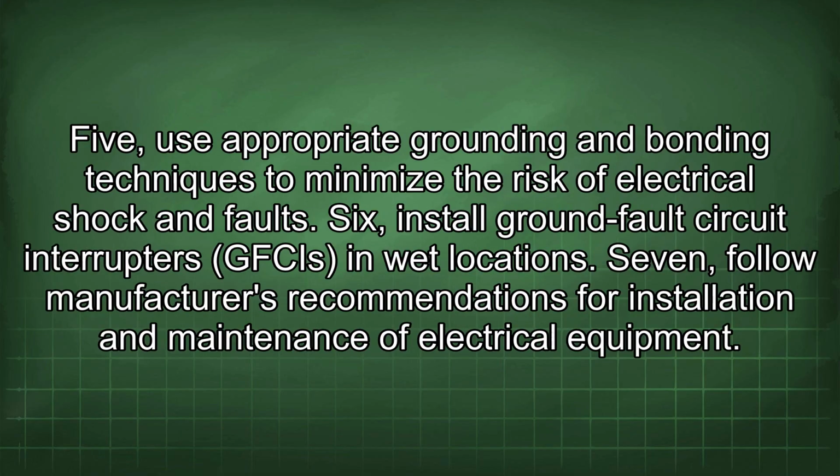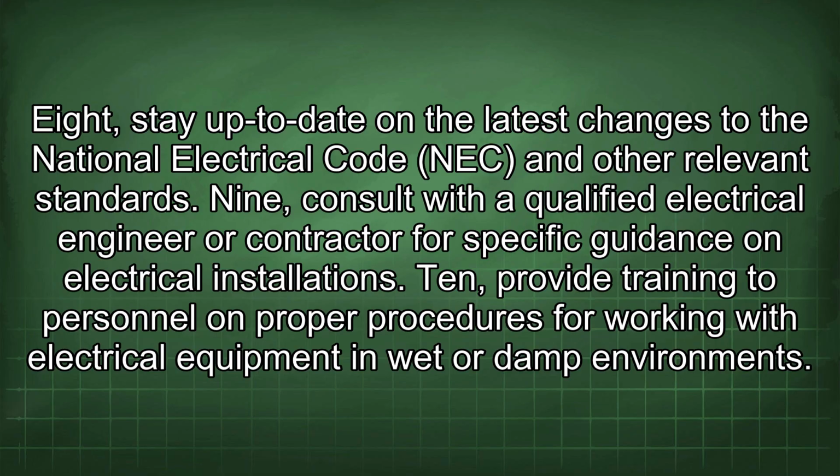5. Use appropriate grounding and bonding techniques to minimize the risk of electrical shock and faults. 6. Install ground fault circuit interrupters (GFCIs) in wet locations. 7. Follow manufacturers' recommendations for installation and maintenance of electrical equipment. 8. Stay up to date on the latest changes to the National Electrical Code (NEC) and other relevant standards.